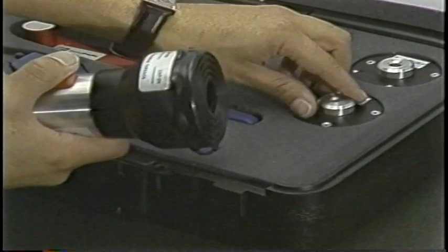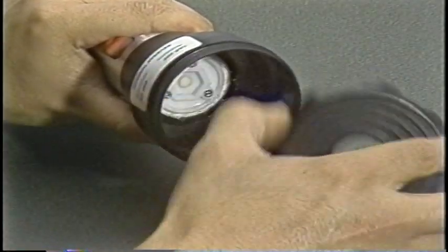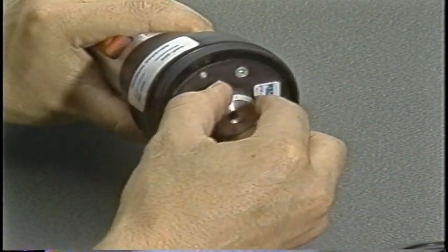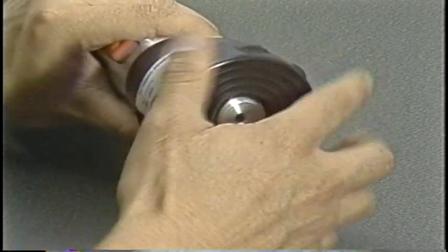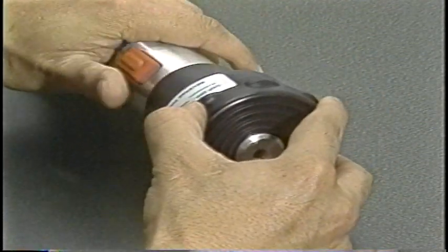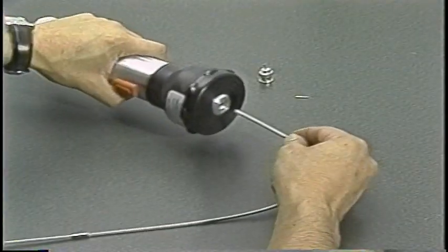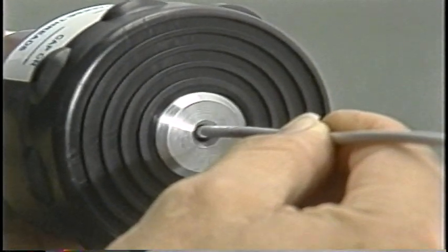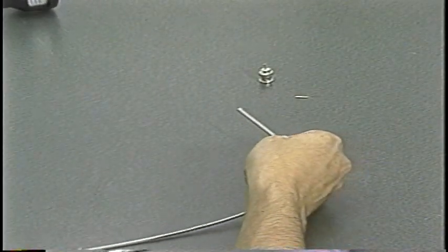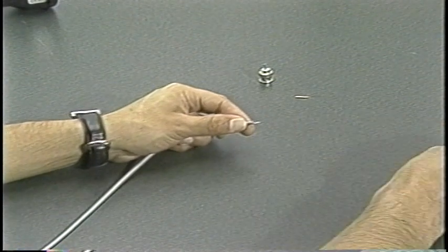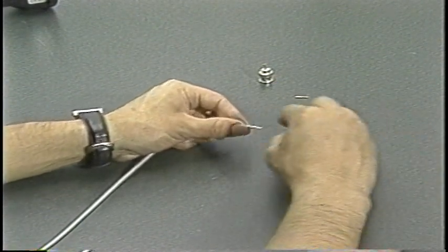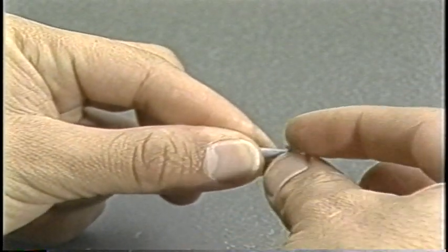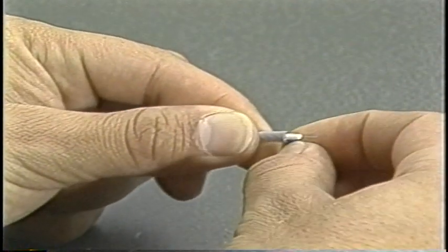Place the automated stripping unit into the AC power pack. Place the cutter head into the stripper unit. Install the cover. Insert the cable into the cutter head and hold it for a minimum of 4 seconds. Remove the scrap ends by grasping them with your fingers and with a twisting motion pull them off. The cut portions of dielectric, foil, and braid should cleanly separate from the cable.